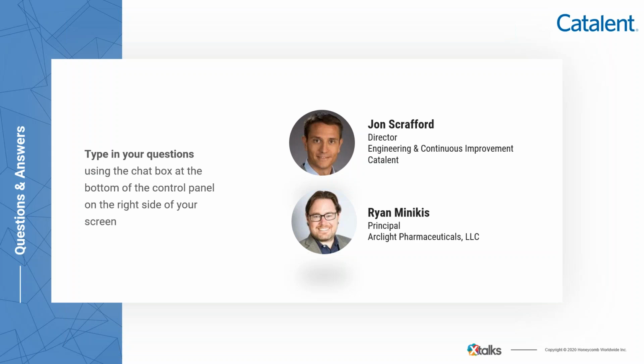Thank you. Our next question here is, as drying is carried out at higher temperatures, how are safety aspects considered? I can take that one. So really, when using organic solvents, the required temperatures are a bit lower, with the inlet temperature generally ranging about 90 to 130 degrees C. When spraying with aqueous feed solutions, the inlet temperature may be all the way up to 200 C. So this certainly does present some safety challenges.